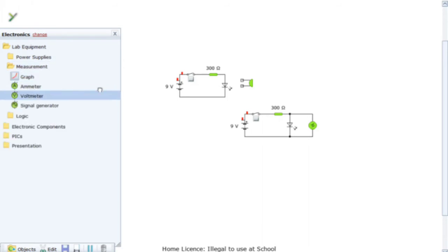And again, for measurement here, just looking at the voltmeter, recording voltage. If you're testing something and you want to check the voltage across something, the voltmeter always goes in parallel like that, and it will show an amount in millivolts this time. And an ammeter, again, need to rotate this, but voltmeters always go in parallel and ammeters always go in series. It's just the rule to make it work, and so that you can record the right information.